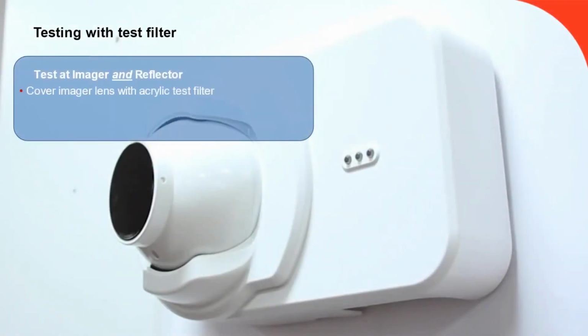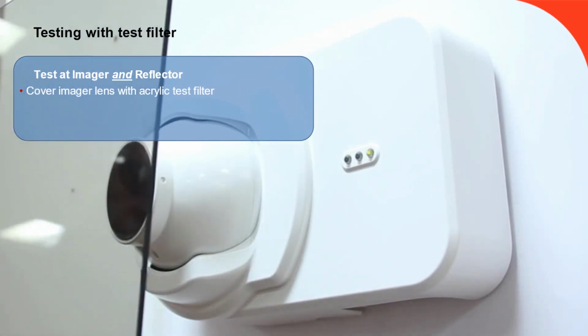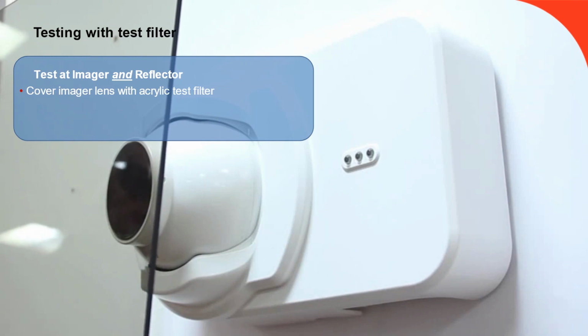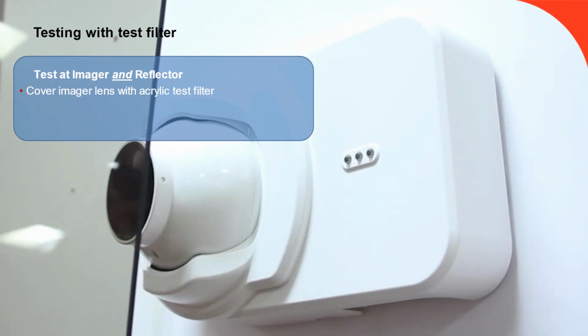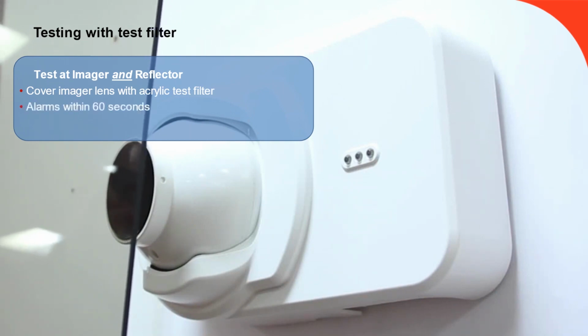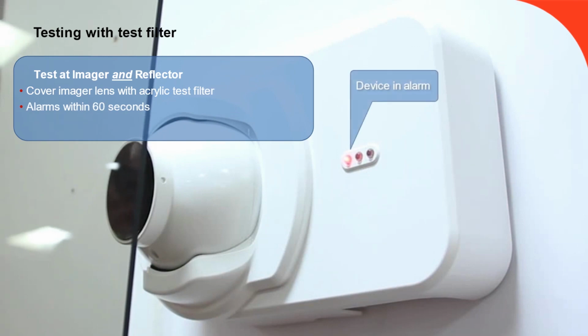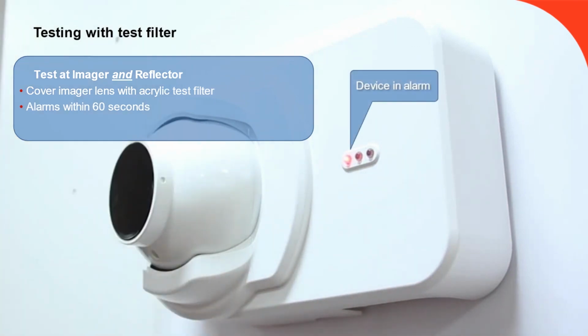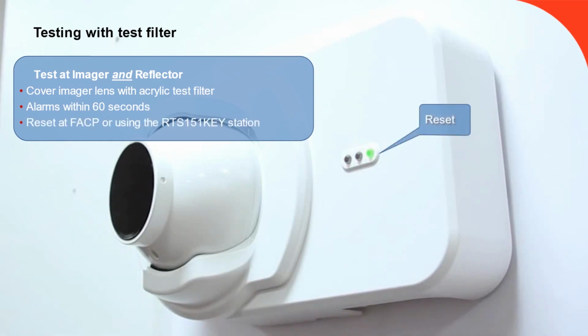Testing with a test filter. While the remote test will confirm the electronics and the connection between the device and panel, to test the optics and configuration, the test filter can be used. This covers the lens, or reflector, and should be held in place for at least 60 seconds. During this time, the device should go into alarm. After removing the filter, the device can be reset. It will now blink the alignment arrows to indicate the set sensitivity. The test should be carried out both at the reflector and the detector.